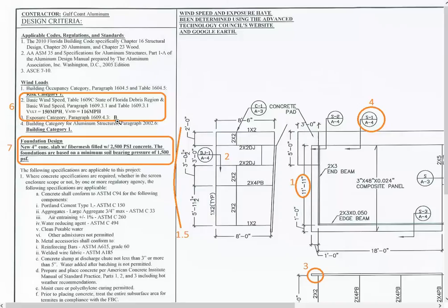And these 2 factors, your wind zone and your exposure category, are factored into your price and your estimate. We consider all these when we're doing the estimate, because the higher your wind zone and the higher the exposure, the thicker the aluminum we have to use to make it meet the wind code, and the more screws and higher quality types of screws we have to use to get the connection details right.